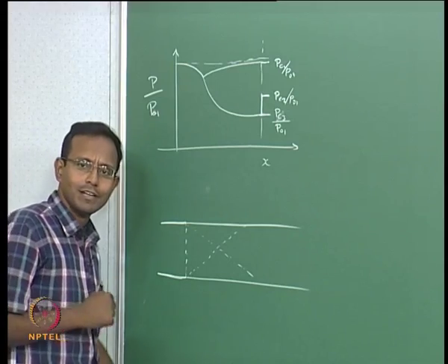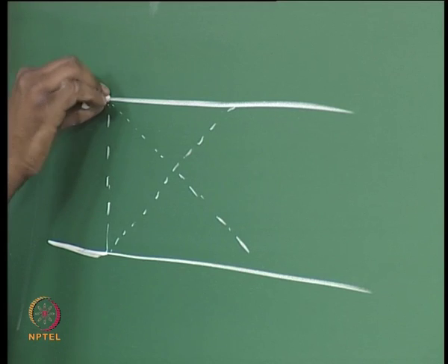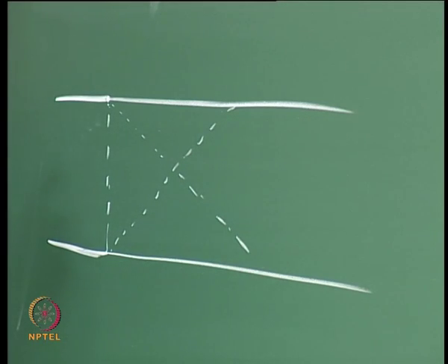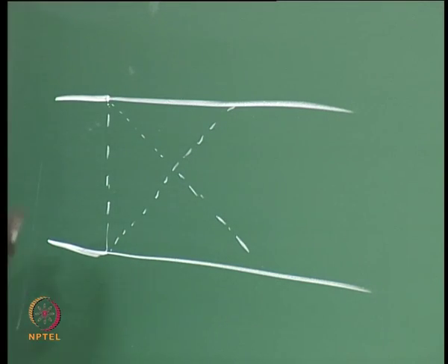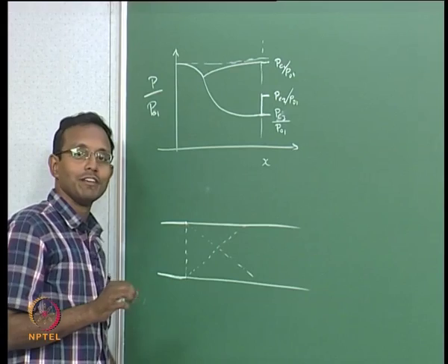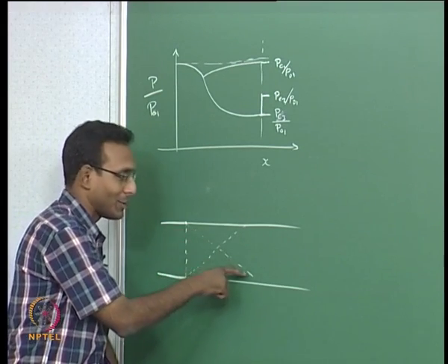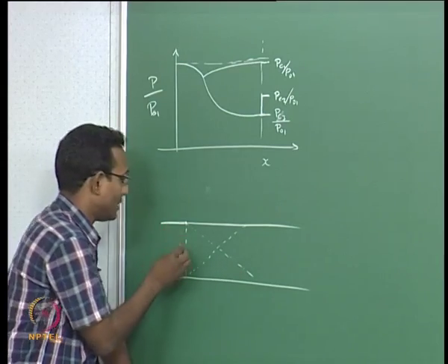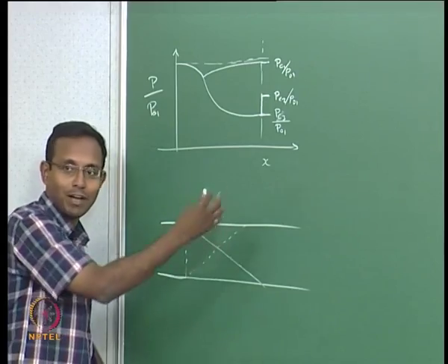What should happen? It should form an expansion fan around this corner, starting from the first point where there should be a change, which is that exit point where it first meets the outside world where there is a different pressure. At that point it is going to send out some set of expansion waves, and the very first wave should be the same as this particular wave you already drew, because the first wave in an expansion fan is the same Mach wave.